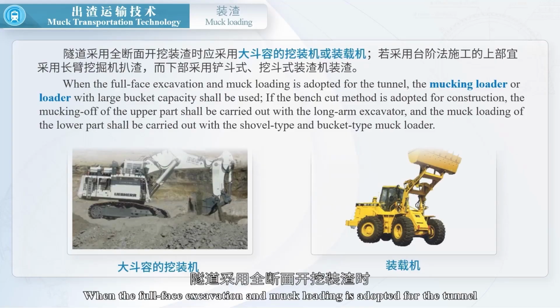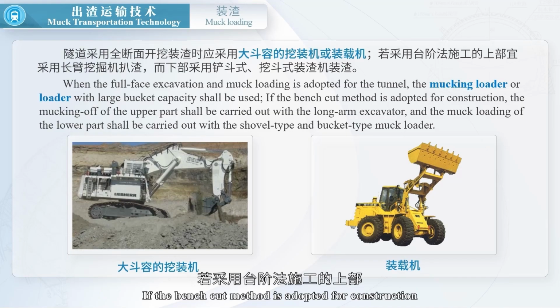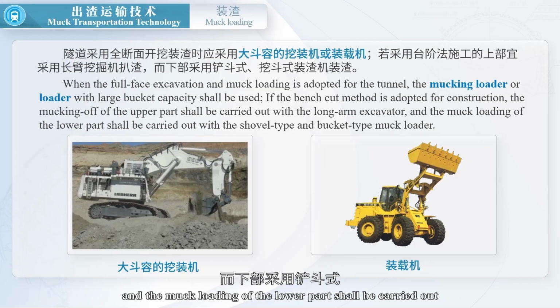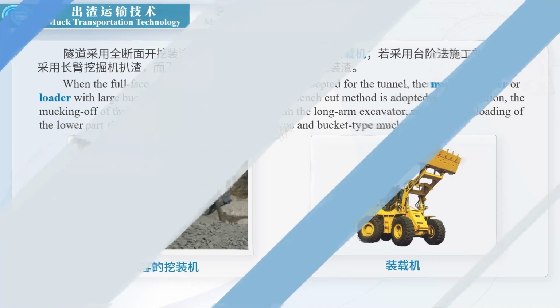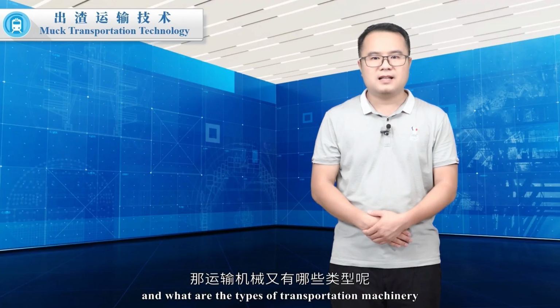So, when the full-face excavation and muck loading is adopted for the tunnel, the mucking loader or loader with large bucket capacity shall be used. If the bench cut method is adopted for construction, the mucking off of the upper part shall be carried out with the long arm excavator, and the muck loading of the lower part shall be carried out with the shovel type and bucket type muck loader. The above are the types of muck loading machines. And what are the types of transportation machinery?